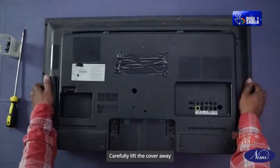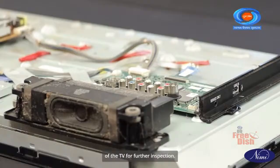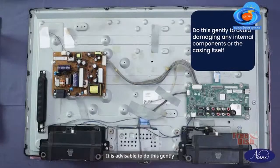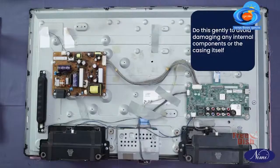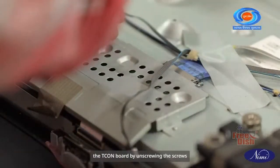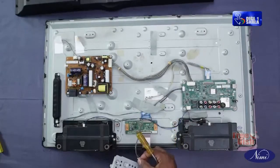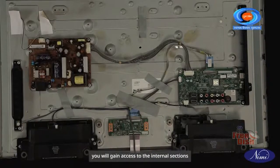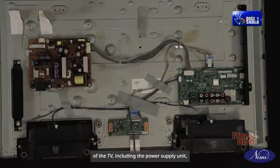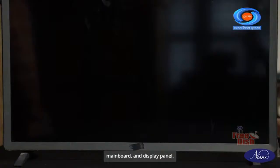Carefully lift the cover away to expose the internal components of the TV for further inspection. Here is a safety tip. It is advisable to do this gently to avoid damaging any internal components or the casing itself. Remove the protective cover from the T-con board by unscrewing the screws. Once the back panel cover is removed, you will gain access to the internal sections of the TV, including the power supply unit, main board, and display panel.